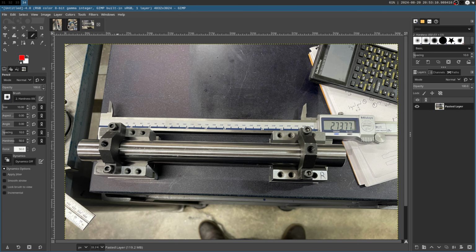In theory, you could build a surface plate setup to scrape the spindle parallel to the base of the headstock, such that you would expect to just lay the headstock directly on a flat thing and they would be in the same plane.